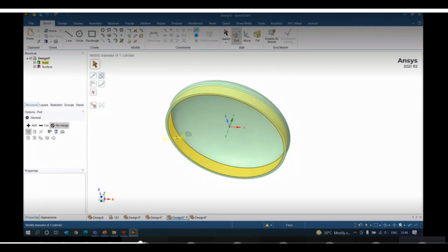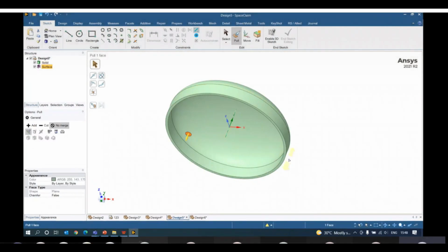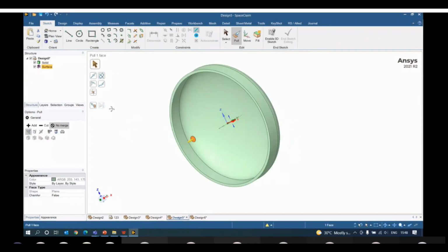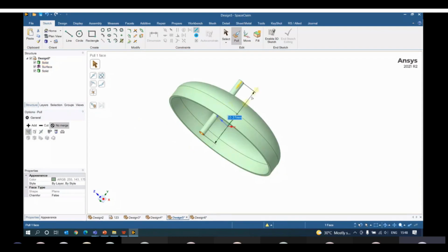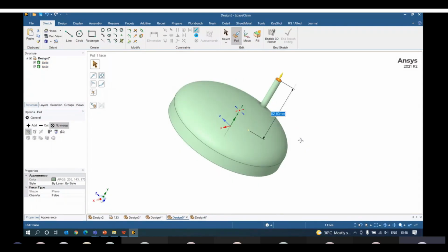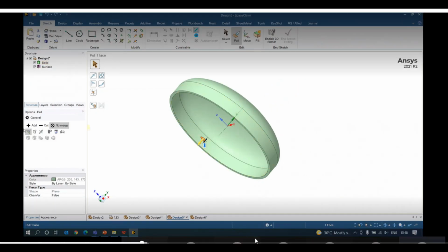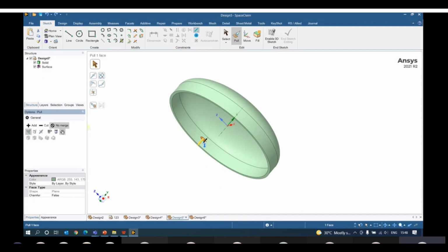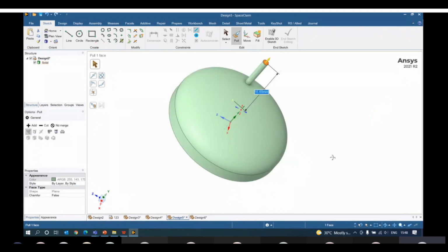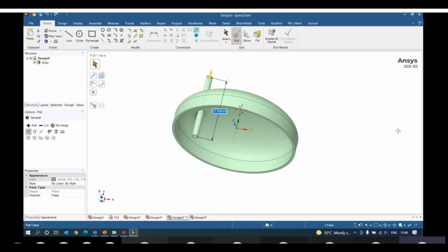Now when you come back to solid mode, your geometry is here. So to create some, okay, so now if I do it in the opposite direction, basically I'm able to create this geometry because it was the positive direction, right? So you can make use of no merge. No merge basically comes in when you're designing two solids and you don't want them to be in a single component. So you can make use of no merge, which we did last time. And when you say plus, directly the same geometry is going to be a part of it and it's going to create.